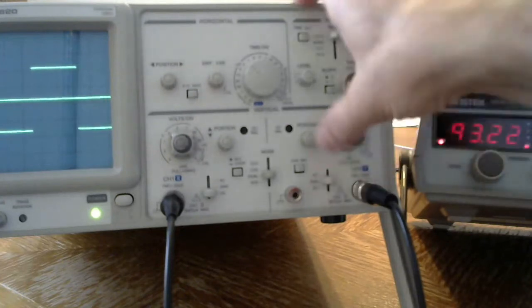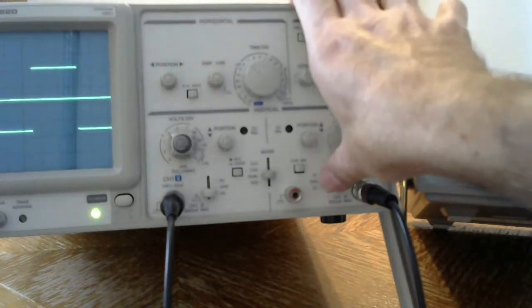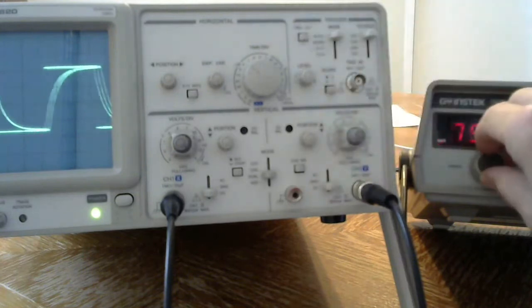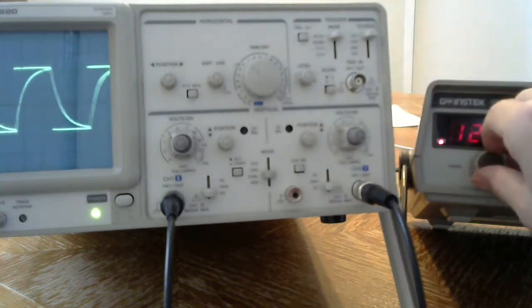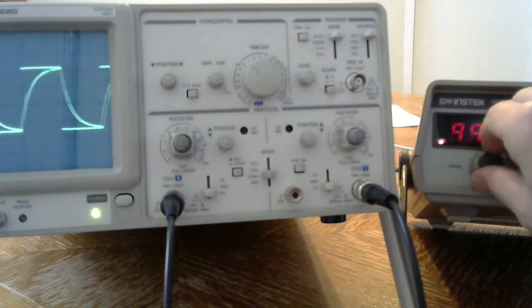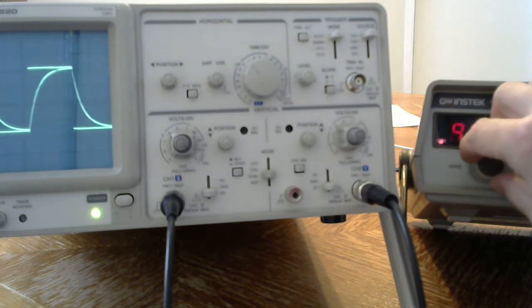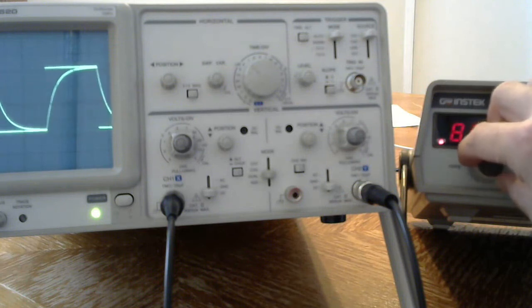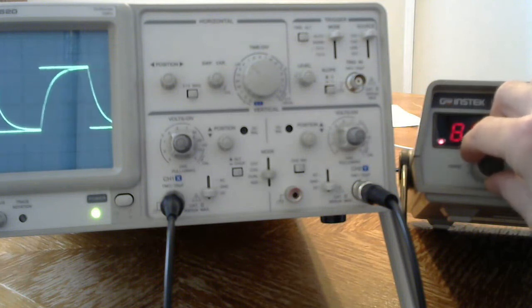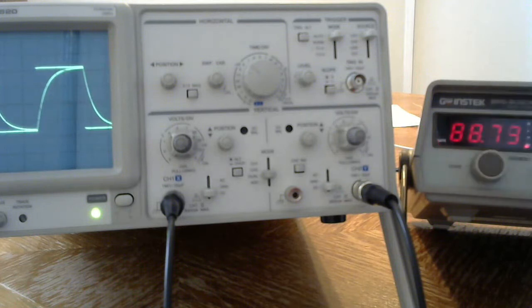If I look at both signals at the same time, you can see how that second signal behaves as I turn on and off more quickly, so the capacitor doesn't have time to fully charge, and more slowly, so the capacitor actually has a chance to charge and fully discharge. Okay, so what I'm doing there is I'm actually changing the signal itself, the input signal.